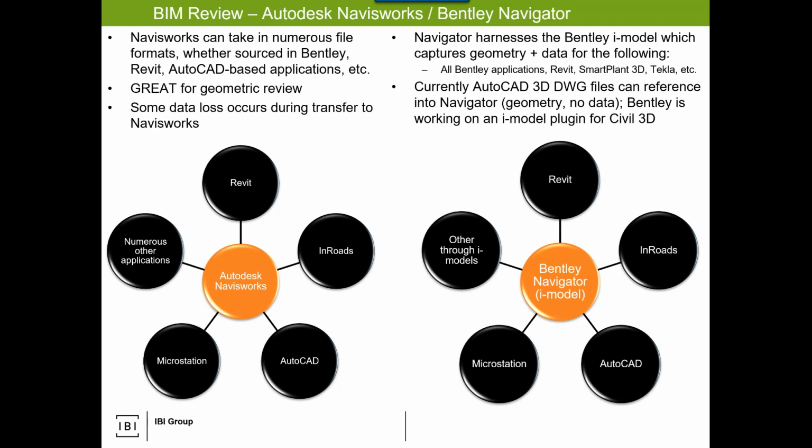So that's a very important aspect of our role. Same with the design review concepts. It's comparing what are we doing? Navisworks, Navigator, other. I didn't list on this slide here, but keep in mind Solibri as a review tool harnessing the IFC file. So that's an interesting workflow and an interesting technical solution that you always have to consider. Are we reviewing based on our live BIM authoring tools, or are we reviewing based potentially on OpenBIM? And OpenBIM is powerful. For the most part, your data from buildings flows. You may have a struggle with engineering data. So as they continue to refine and enhance the ISO standard that governs the IFC file, going out of these proprietary tools, Autodesk and Bentley, to something else like the IFC file and thus into Tekla BIMsight, Solibri IFC viewer, makes it far more viable in the years to come.